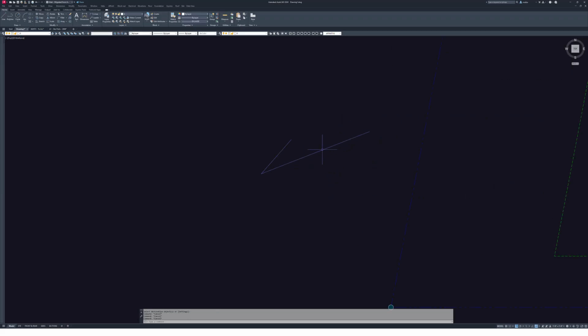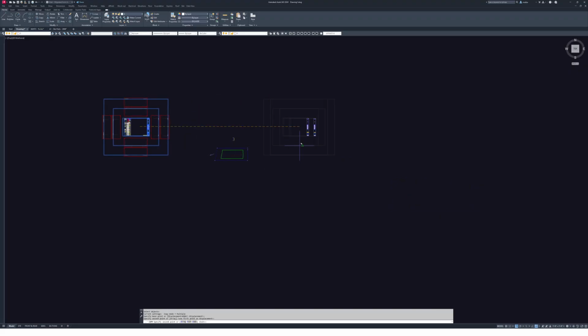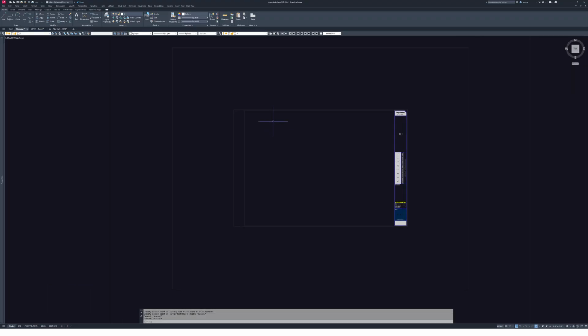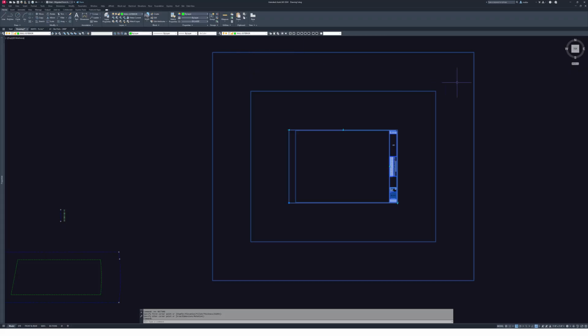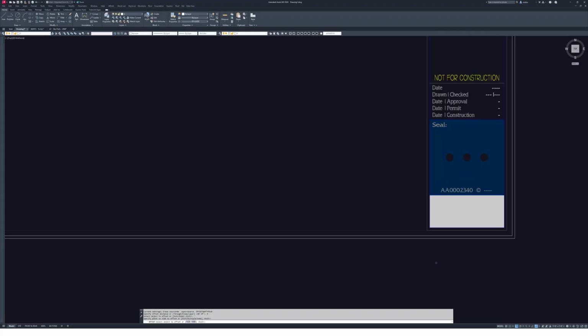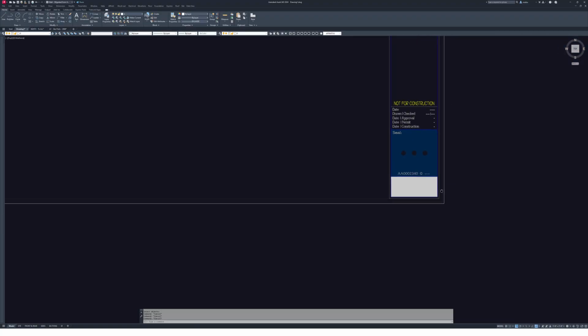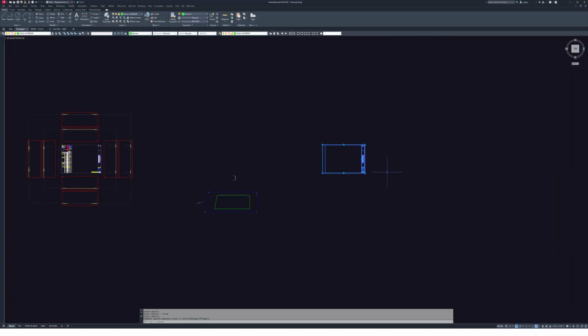So now we have this north arrow, and if we're going to start making a page layout, the first thing I want to do, and I usually do this, this is my page layout, and these are old school drafting way of doing elevations where you can actually rotate around the plan. We used to do elevations that way, but we don't really do that much anymore, so I'm just going to clip those out. So I'm outlining my page, offsetting 4 inches, and then doing X clip, clipping my page, saying new, and then select polygon, select that one, and then, so now they're clipped out.